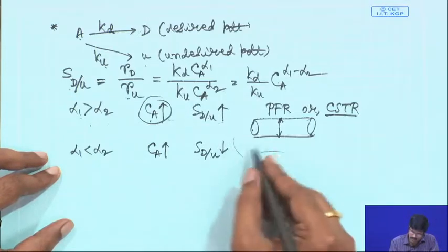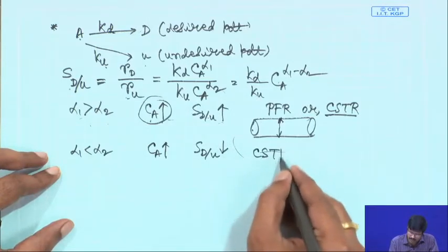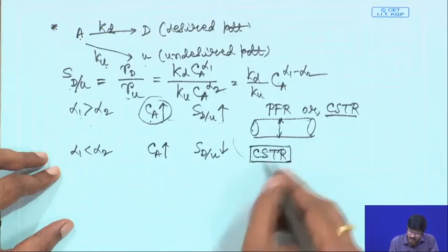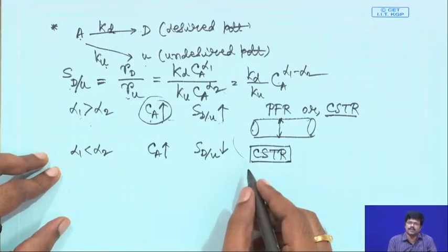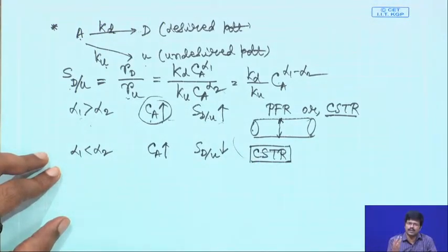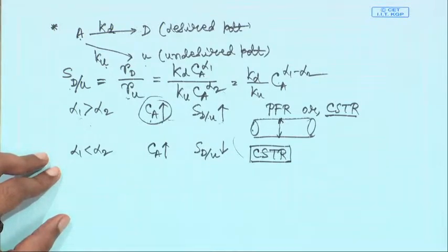In that situation, you will basically use CSTR, where your reactant is in diluted condition. You are doing the reaction at a lower concentration of your starting material, because the reaction is already in progress and in steady state. So, conversion does not change, the targeted conversion whatever you are looking for, and the concentration of reactant is a diluted species, because it has been diluted into the reaction mixture after coming through the feed stream at a higher concentration. So, the concentration at steady state does not change.